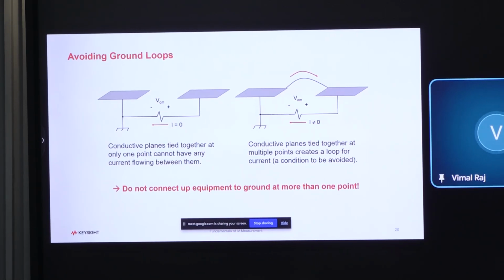Leakage through multiple paths will also get reflected in the measurement. To avoid multiple grounding, use one closed loop system. One closed loop system will give a more accurate, steady current.